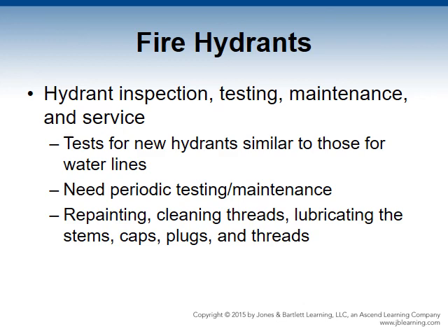Once installed, fire hydrants need periodic inspection, testing, maintenance, and service to ensure proper operation. Making sure that the hydrant is accessible, checking the hydrant for damage, and the body, hose, and threads all make up this inspection. They also need to make sure the hydrant operates properly and make sure there are no worn parts. Hydrant maintenance consists of the following: painting and repainting when necessary, cleaning threads, and lubricating the stem, caps, plugs, and threads.